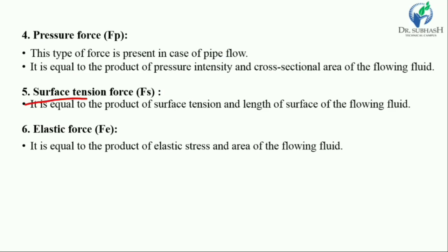Now next is the surface tension force. It is also an important force for fluid mechanics problems or model analysis problems. It is equal to the product of surface tension and the length of the surface of the flowing fluid. It is a very important force in fluid mechanics. Elastic force is also an important force. It is equal to the product of elastic stress and the area of the flowing fluid.